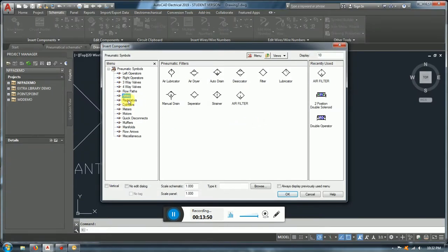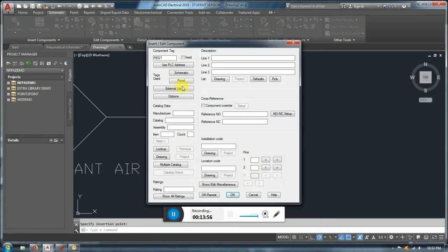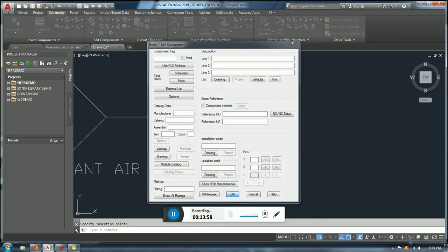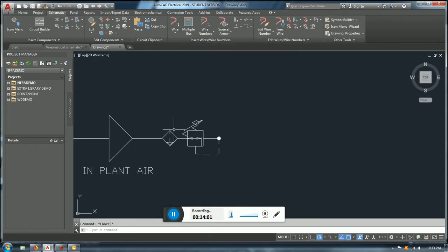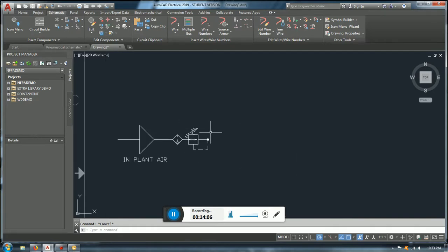Why do we use regulators? Because the pressure that you're gonna get from the plant, you don't know how much it is. Okay, and you want to know how much pressure you're getting. To know the cylinder sizing, sizing everything. You're gonna have pressure losses. You're gonna have a lot of calculations that we will do one day. In another video, I will explain how to do them. And you're gonna have a lot of calculations, and you want to know how much pressure. And you also want constant pressure. So yes, maybe you're gonna get 100 psi, talking in US,